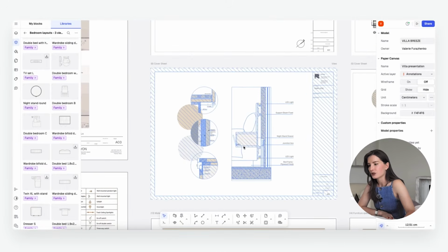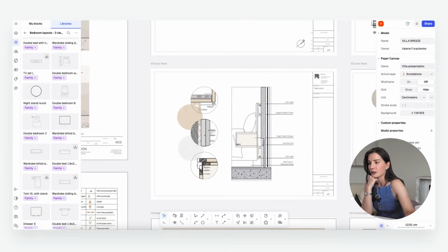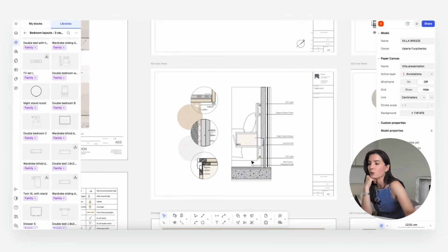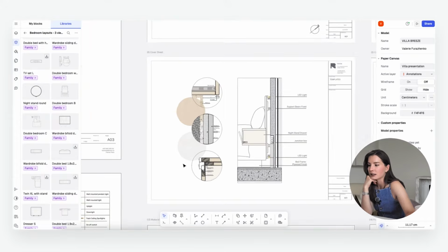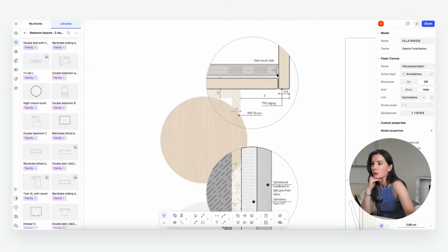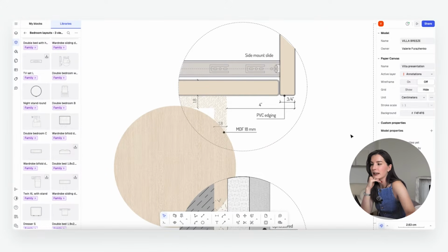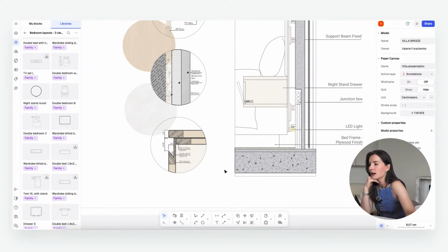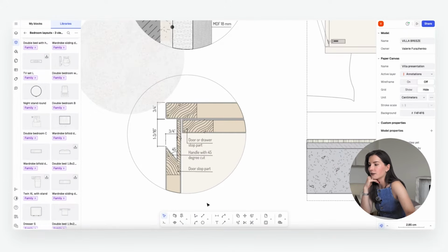Okay, and the millwork drawings. This is again the bedroom configuration. This is a custom headboard with the nightstand drawer. So we do need a little bit more specificity on what's been done, how it's been constructed, and you can actually see how detailed these drawings are. And we give all information we possibly can to the fabricators, to make sure that we are on the same page, and they can flag any kind of issues that they might have on their end as well.